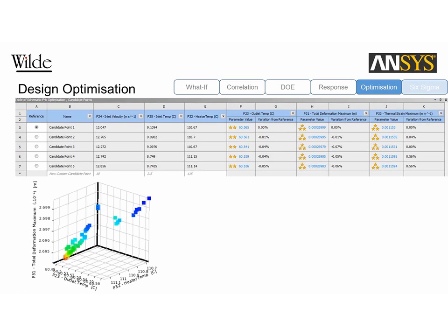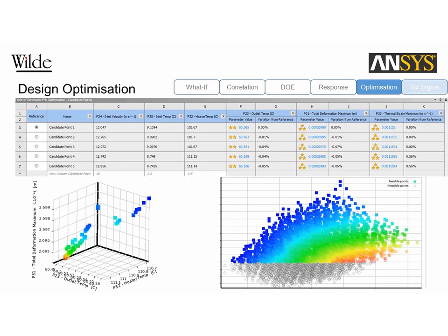So if we plot that in a 3D space, on a 3D graph, we get the design points and the values. And you've probably seen this in 3D or in 2D format, and this is the Pareto front graphs. The blue points signify candidates that are feasible, and the red points signify candidates that are non-feasible, and the gray circles are those that are simple non-starters to begin with.